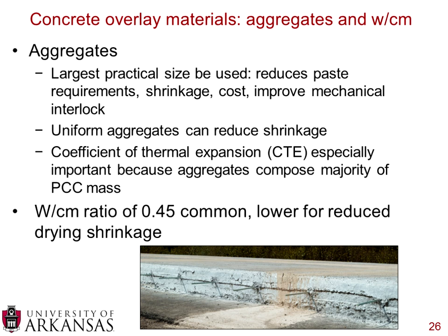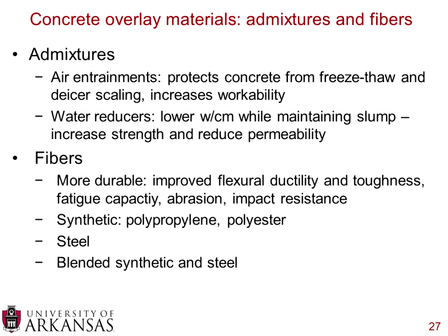For the water to cementitious material ratio, 0.45 is common, but you can lower that if you want to reduce drying shrinkage, and you can also lower that if you want to expedite the curing and return to traffic.